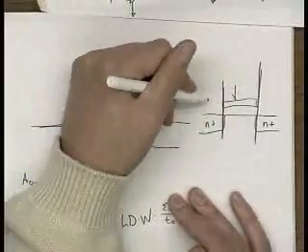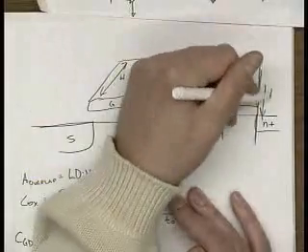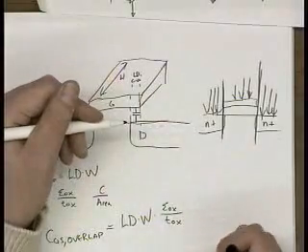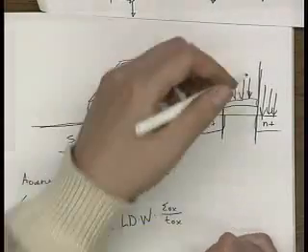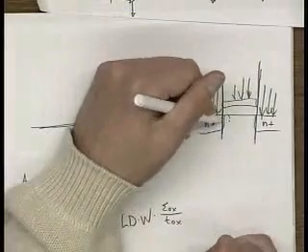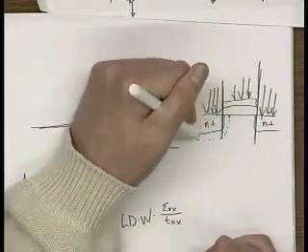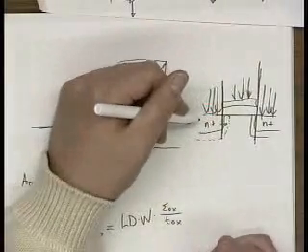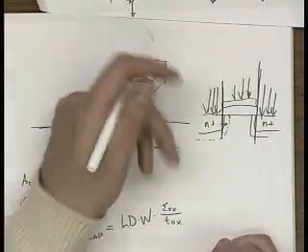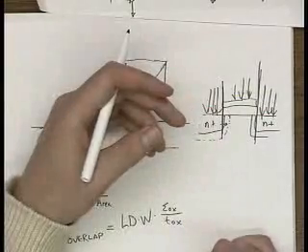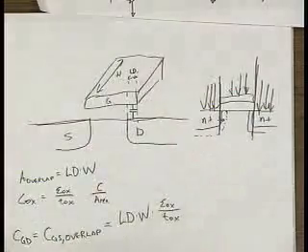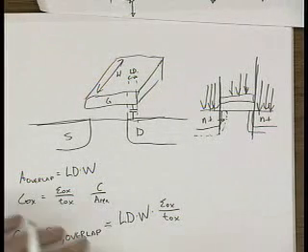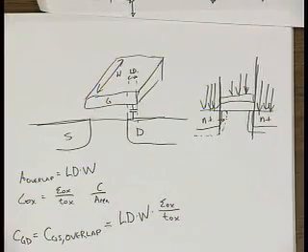And then they usually do a heat annealing, and that creates a lateral diffusion of these particles. There's nothing you can do about it because after you bombard with an implant, you've messed up the crystal structure of silicon. So you need to heat it to enable it to re-anneal. So there's nothing you can do about that overlap.